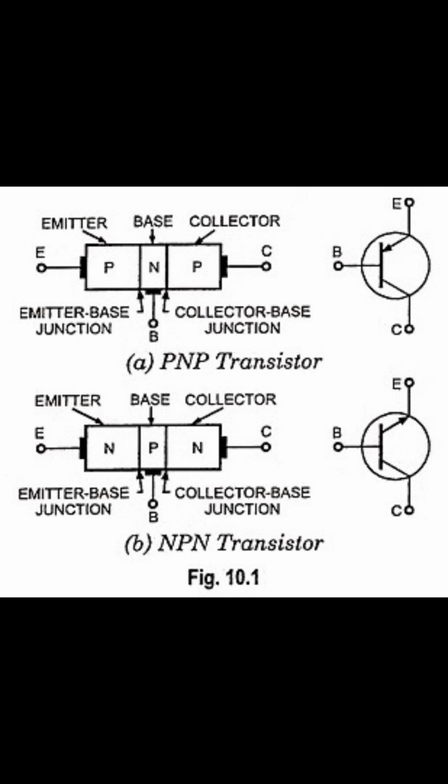Now, in summary, the types of BJTs. In the NPN transistor, the majority carriers are electrons. The base controls the transistor's operation with a small input current. The collector receives the output current, and the transistor amplifies the current. The emitter and base are forward biased, and the emitter injects carriers into the base, allowing larger current to flow from the emitter to the collector. Next, the PNP transistor.